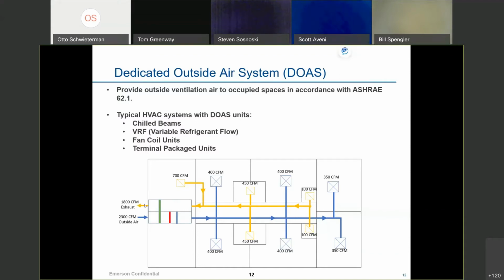and it's going to leave at a higher temperature because of this outside air. So this outside air might be 90 degrees outside and 70% humidity. But this heat wheel will cool this outside air down; it'll condition that air. So this outside air may be 80 degrees and 65% humidity after it goes through that energy recovery wheel.